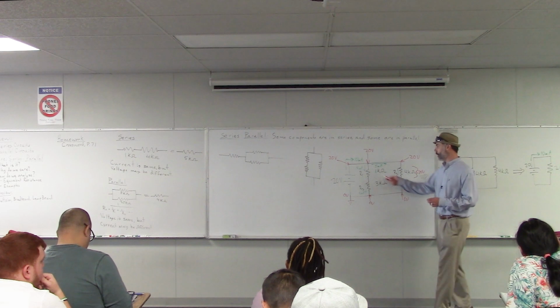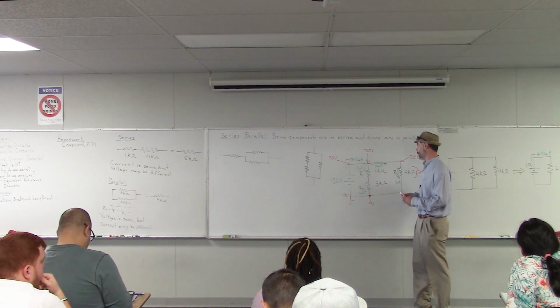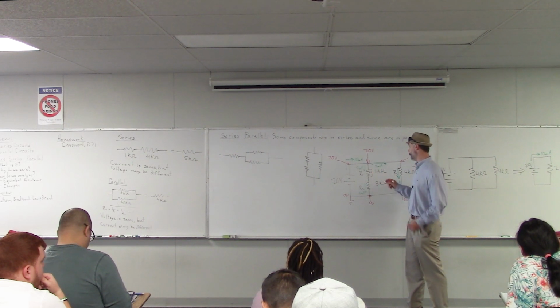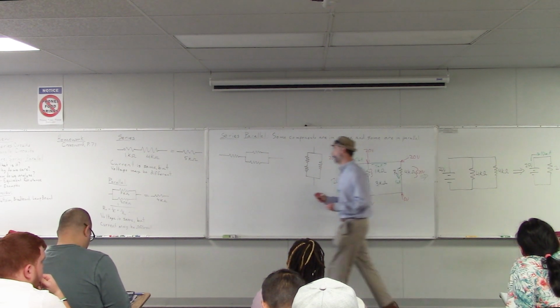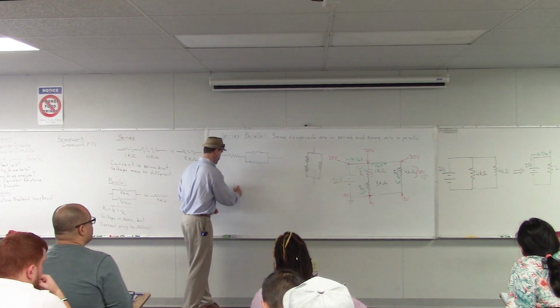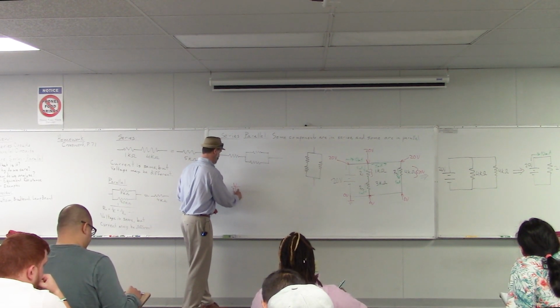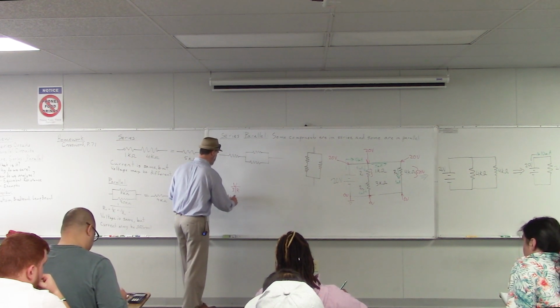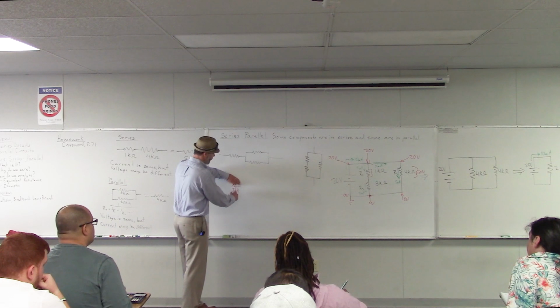Now we know the current for R1 and we know the resistance, so can we find the voltage? Yeah. So we'll use Ohm's law for that again. So we'll write down V, I, and R. That's Ohm's law. If we want to write down the voltage, we write down V equals, we cover that up. We see that it's I times R.